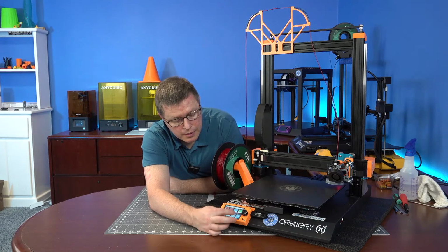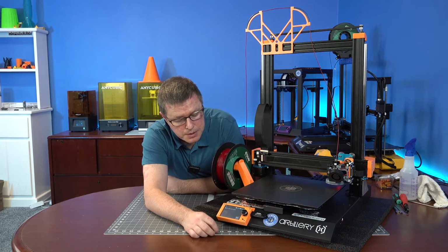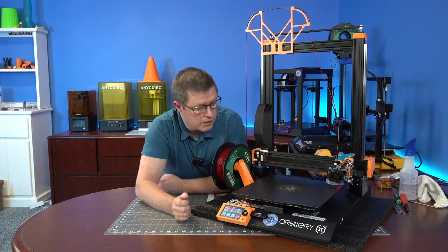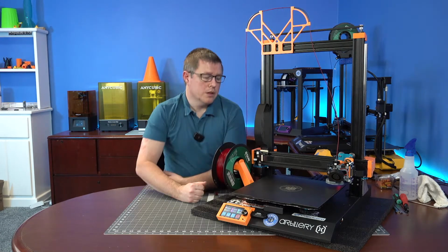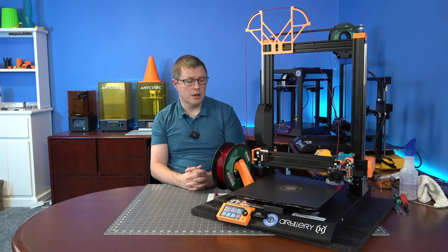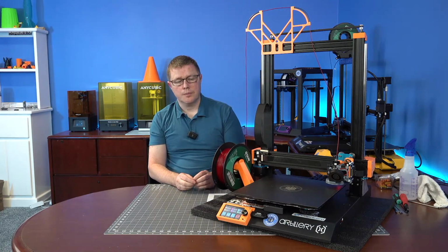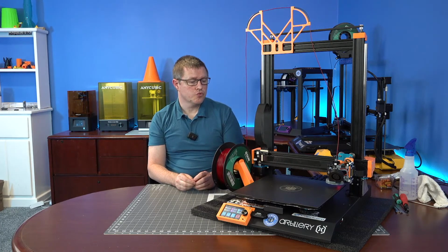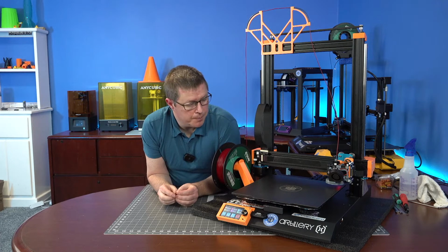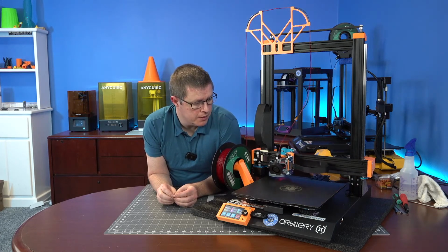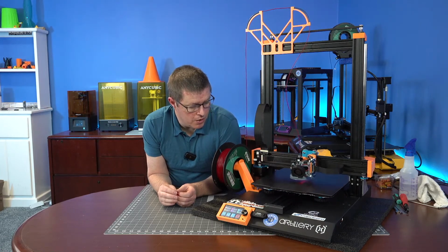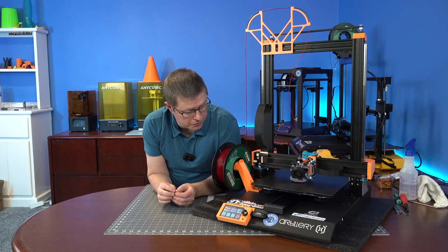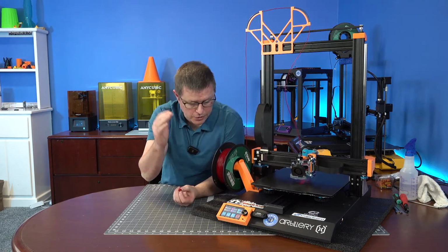Okay, print, USB stick, level test, go. Is it going to heat up to 70? Yeah. So it's heating the bed up a little warmer for my test print, but it should rehome and compensate for any bit of thermal expansion the bed has gotten from that extra 10 degrees C.